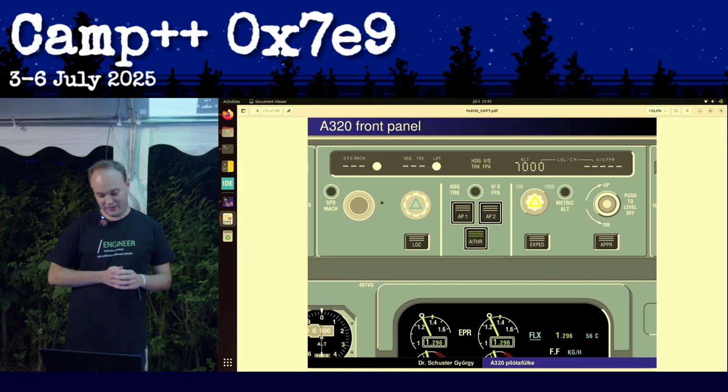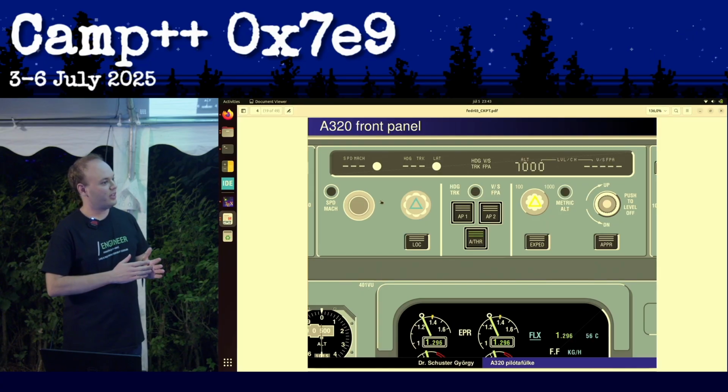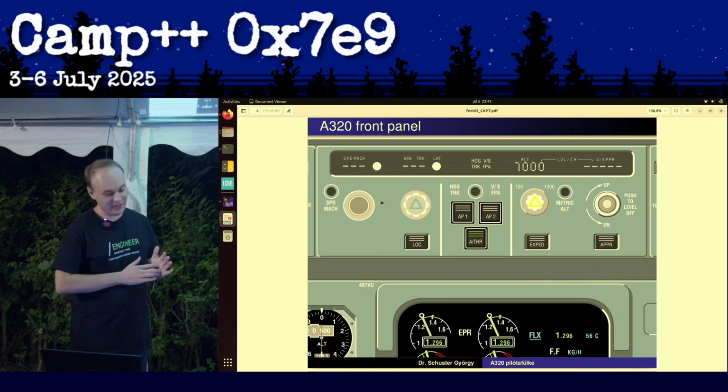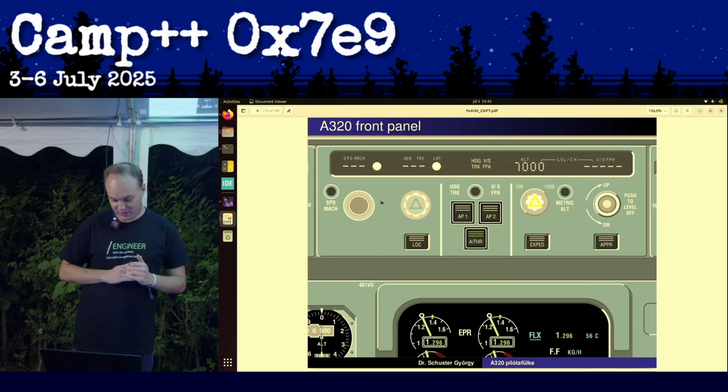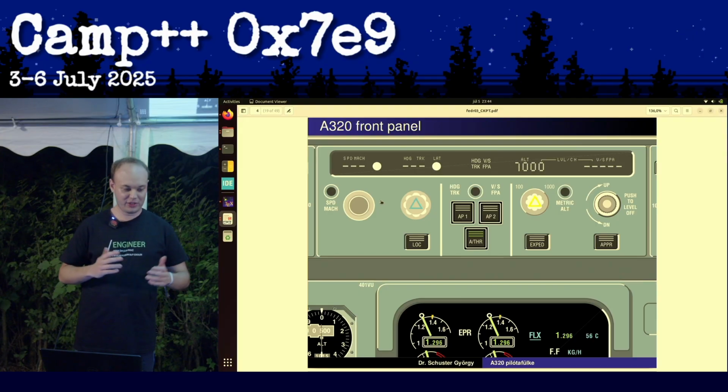And autopilot basically, on top of keeping constant speed, the main purpose of it is to keep a constant bearing and constant altitude. In its very prime functions, that's all it does. There are two autopilot systems, and there's also the auto throttle that controls the actual throttle levers, or actually doesn't move the throttle levers, but it controls the throttle.